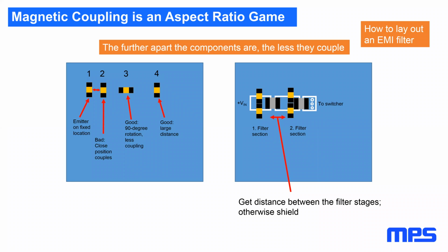So how can you improve your filters if you do them? We learned now that capacitors couple with each other magnetically or in a transformer way. So in order to get a good filter action, just move one capacitor from the other with distance, or turn it 90 degrees. So good distance is good.